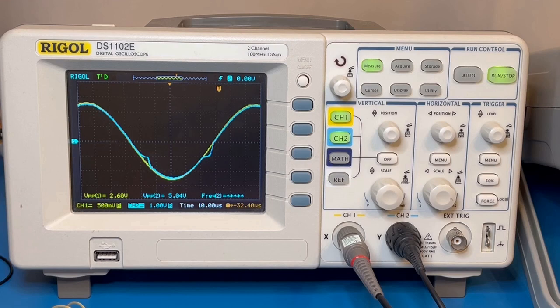One conducts power only from the high side rail, VCC, while the other conducts power only from the low side rail, VEE. This means that when the output voltage goes from a high voltage to a low voltage, or a low voltage to a high voltage, it has to turn one transistor off while turning the other transistor on as it passes through the middle region. This results in a highly nonlinear region right around that transition point.